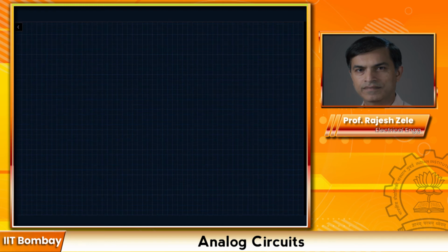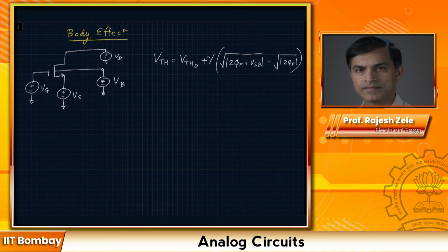I would like you to recall what we learned in the earlier lecture for the MOSFET, which is called body effect. So body effect, let me write it again. So this is a recap from our previous lecture. What this is telling you is the threshold voltage of the device changes depending upon the potential difference between body and the source.